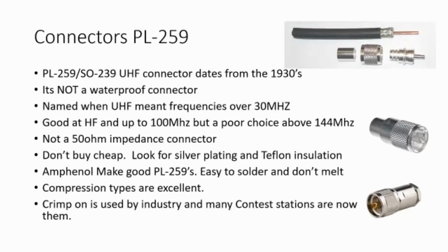So from cable, we'll move on to connectors, because connectors can be as important as the cable. No point buying very high quality cable and putting nasty cheap connectors on it. The PL259 dates back to the 1930s, believe it or not. The standard PL259 is not a waterproof connector. You need to make sure it's well insulated with self-amalgamating tape and insulating tape to keep the water out of it.